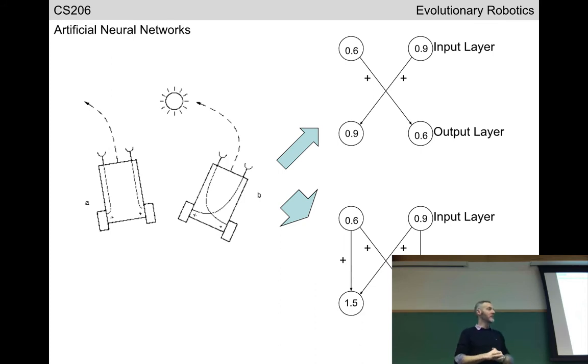So in the bottom left, I've started to add some additional wires, which are not actually wires, but they are synapses. So synapses in biological tissue are the connections between neurons. They pass signals from one neuron to the other. Our synapses here we're going to represent as these lines that pass signals from sensor neurons to motor neurons.